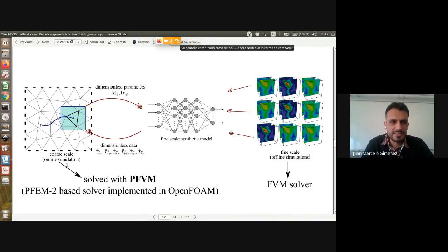We can use a standard Eulerian approach in the coarse scale. It's a tradition of myself and Sergio's school, because we know that Lagrangian approaches solve the convective terms better, and we must convect the turbulence data to carry the turbulence states. That's the main reason, but an Eulerian approach can be used also.